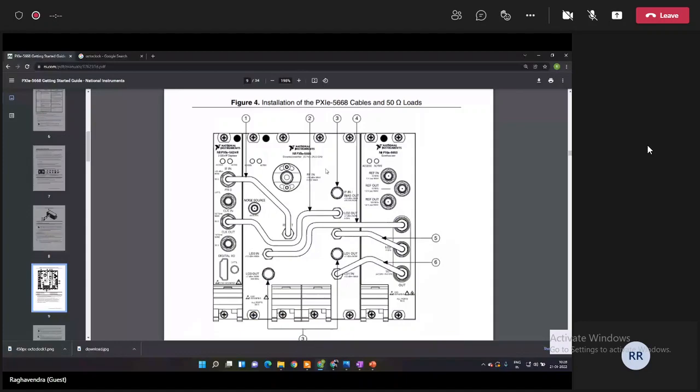What this does is, this is a down converter system that takes whatever input you give. You have an RF input over here. This could be a wire, an antenna, anything. Whatever comes in, it takes that signal and down converts it to what we set it to. This doesn't directly give us the baseband signal. What it does is down convert this into an IF signal, to a frequency where we will be able to actually process it.